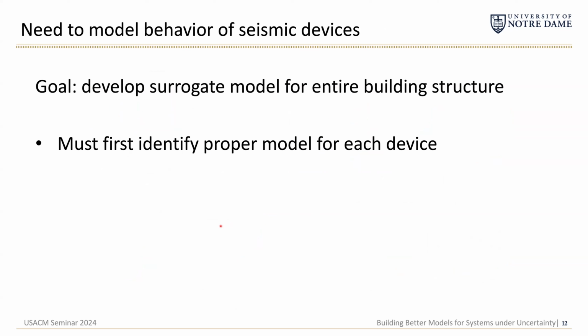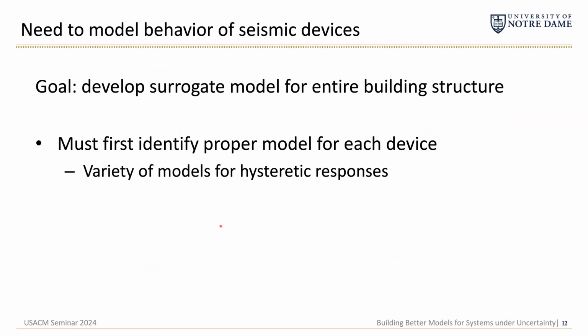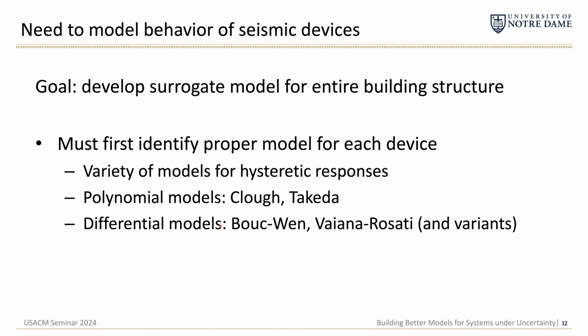And so we have to then identify a proper model for these devices. And there are many models that we can consider because there's many ways you can model a hysteretic response. We could use polynomial models such as the Clough or Takeda model, very classical approaches. There are differential-based models like that suggested by Bouc-Wen and very recently by Vaiana and Rosati.